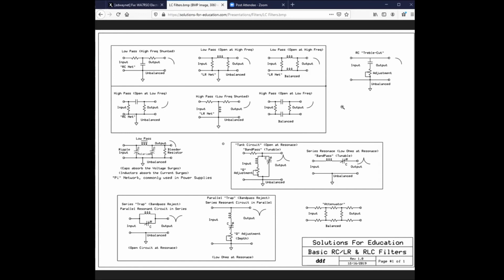And by the way, we did something where we were way ahead of the industry, and I'm just fortunate to have had a part in it. One of the guys got an idea. Actually, a team of the engineers at the Space Center got this idea about how to calibrate these tables. They came up with the idea of sending what they called a calibration pulse down to the table, and then looking at the data that came back and doing a Fourier transform on the data difference. Then they would do an inverse transform to fudge the signal to compensate for that, so as to tweak it to get what they wanted.